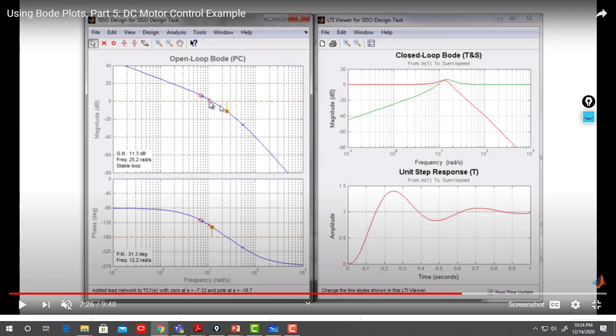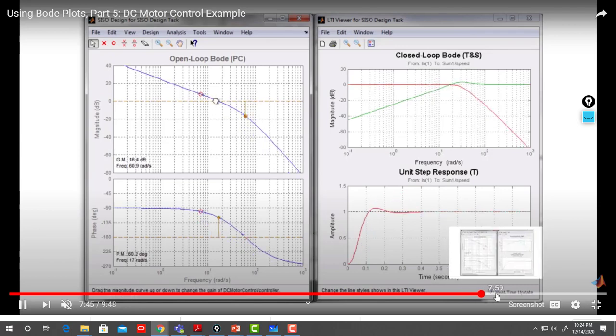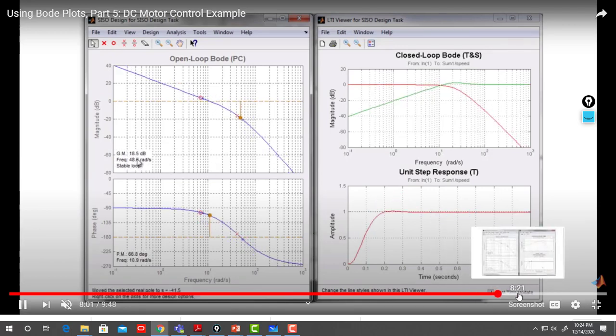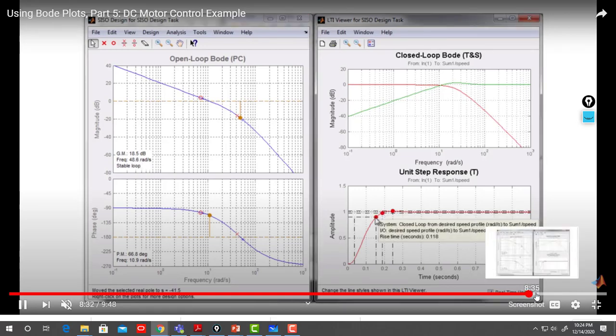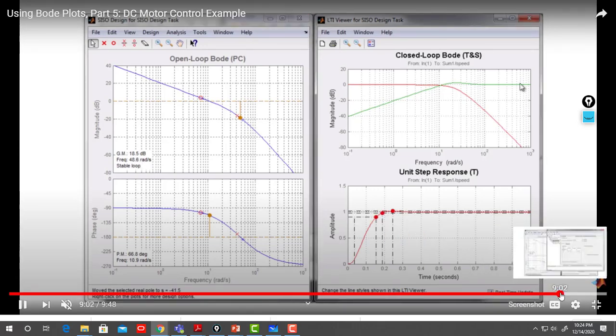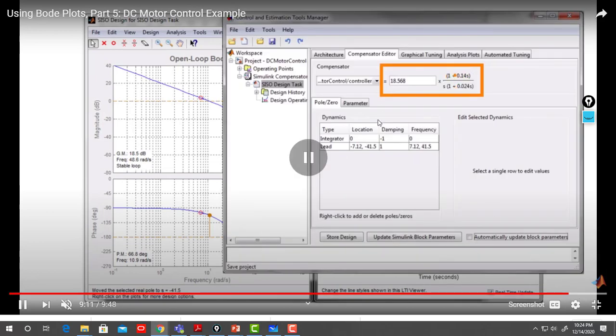So you can adjust the difference between the pole and zero. You modify your system to get the desired sensitivity and complementary sensitivity, reduce the overshoot, etc. Okay, so you can follow here really the link to see how he is doing them to verify and get the required design requirement, and at the end he gets that system: pure integrator and lead lag compensator.